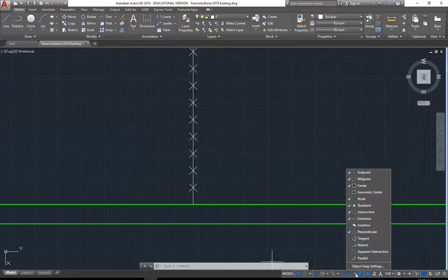So down here, you've got object snap, and then node needs to be on. Yeah. So, yeah, 17, that's right. Okay, so is your floor-to-floor height 3 metres? Looks a bit high. You might have offset up from there instead of down.